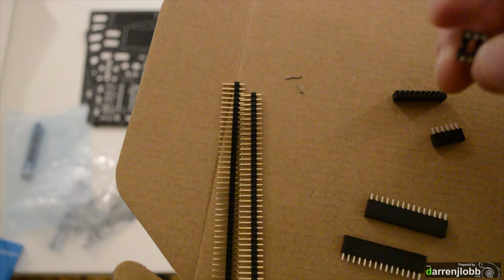One last thing to note is R8 is marked as a resistor. It's marked down on the text file as being a 0 ohm resistor, so you can just wire a piece of wire between those two pins. I'm actually just going to use one of the legs of a resistor that I cut off, put that down through, bend it and solder that in there.